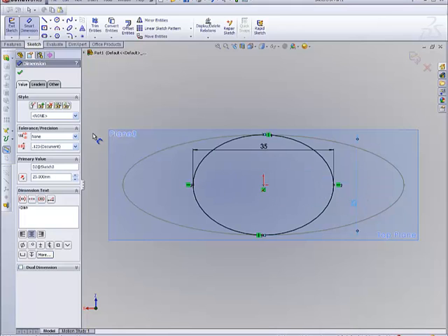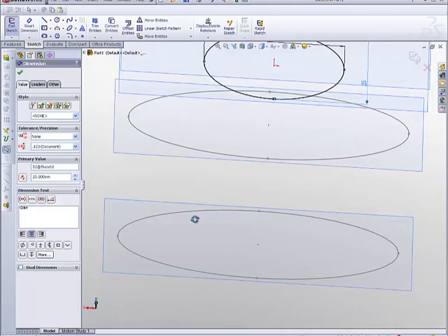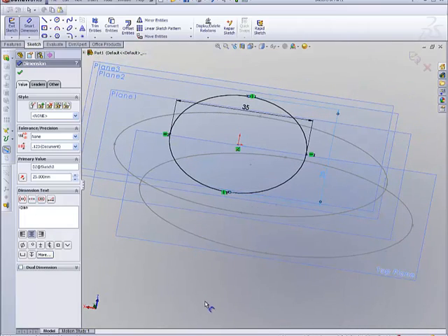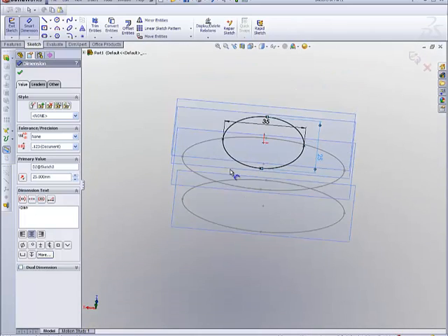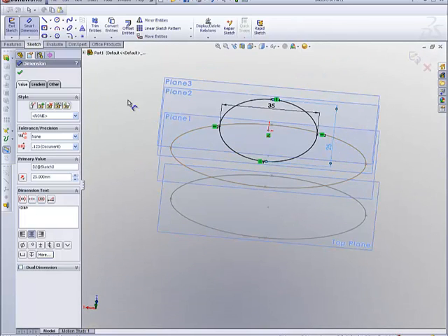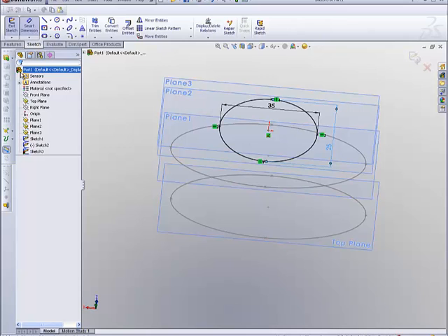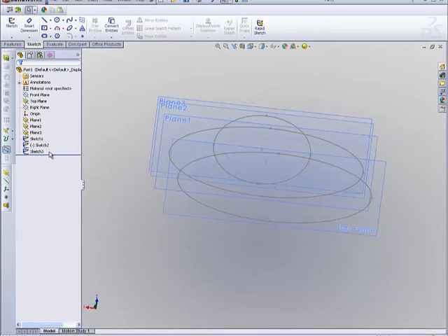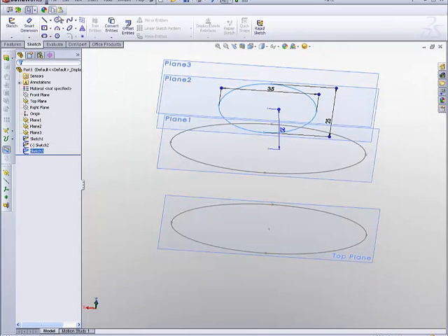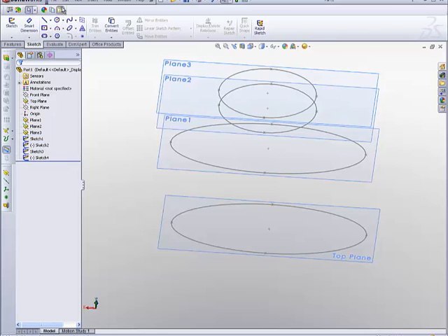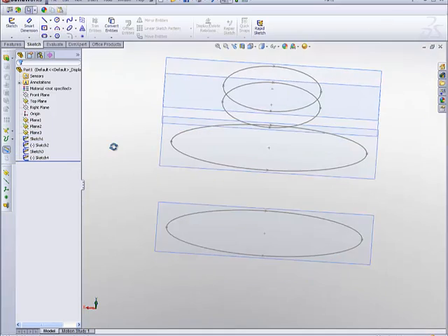This may be a little odd, but if you look at it, it'll make sense because it will then build up into this little portion, like so. So now with that all set, click OK and exit sketch. Deselect, then select sketch 3, click copy again, and then click plane 3, and click paste. And we got our planes.